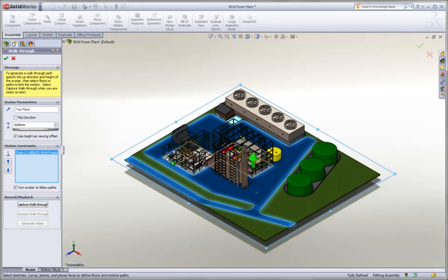So I like to grab the asphalt on the outside of the building, the inside floor of the building, and then with my Show Sketches hotkey, I'm going to grab this sketch here as well. Now you'll notice that the sketch that's visible is one continuous spline. It makes it much easier for selecting an entire path instead of going into my Feature Manager tree and having to select a sketch to get all the entities. I'm going to turn off my hotkey to hide that, just so that I don't view it when I go into this. And then finally you simply say Capture Walkthrough right here.